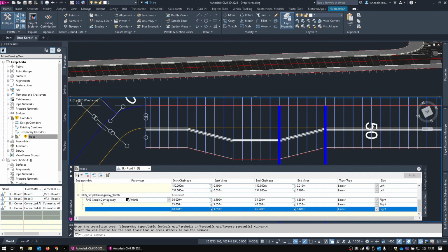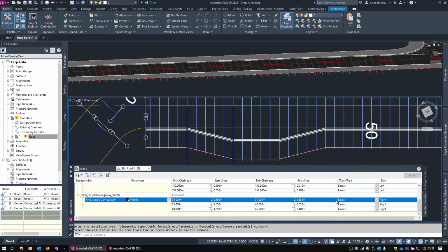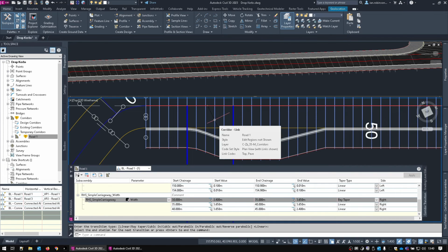Now, while we're at it, we can simply adjust these. I mentioned all these different types of bay taper. Apply, you'll see it'll curve in there. Now, interestingly enough, if you don't have lots of assemblies in there, it won't actually do anything. If there were no assemblies, it will just be a taper no matter what you're setting here. The more assemblies in here, the more rounded you will get. It doesn't add the assemblies afterwards.